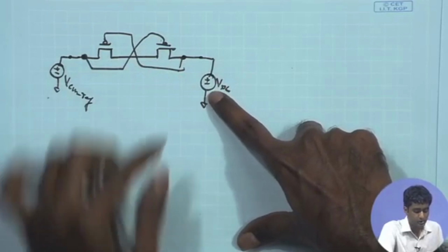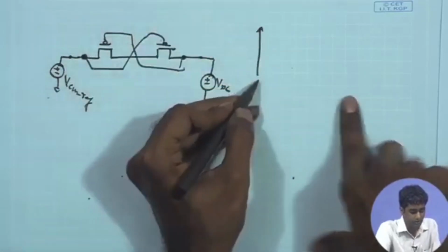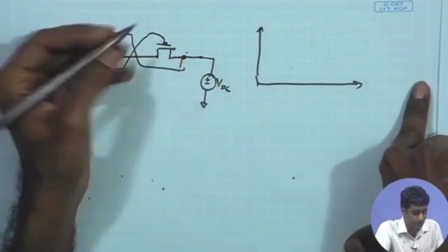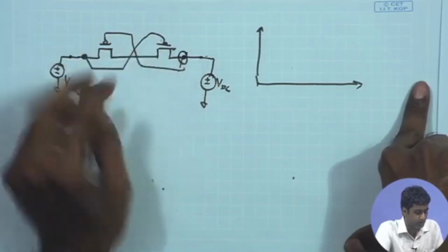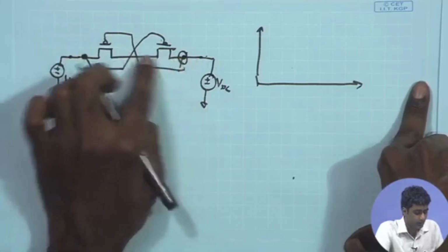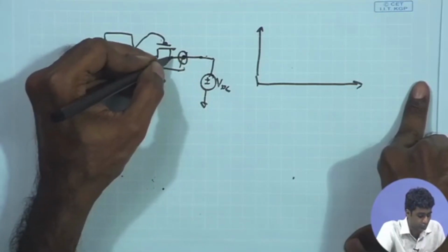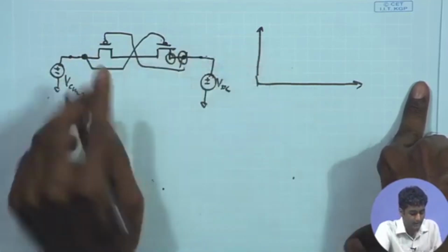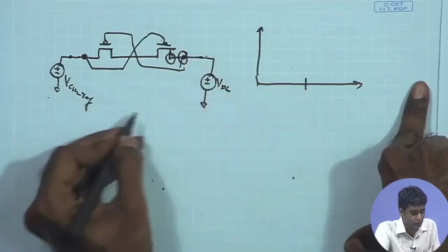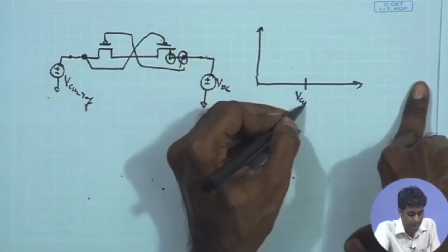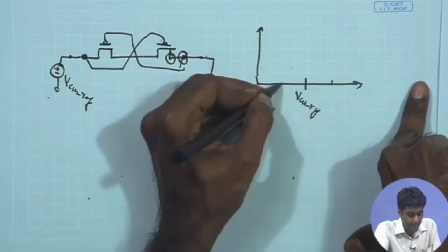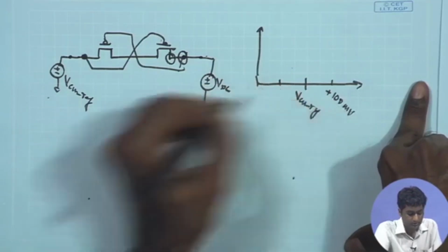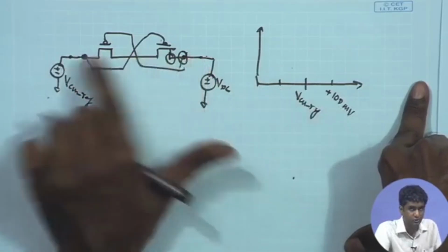look at the overall variation of the current across these resistors. So, you can put a marker at the source of this PMOS, and then plot the overall I as a function of VDC. So, VDC needs to be swept across VCM ref. So, VCM ref plus minus say 100 millivolt or even a few tens of millivolts, because remember these two potentials are not going to change too much.